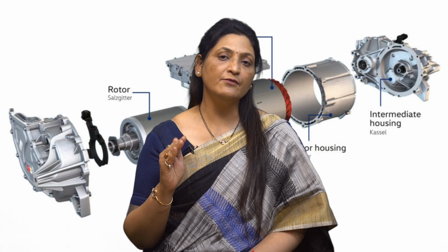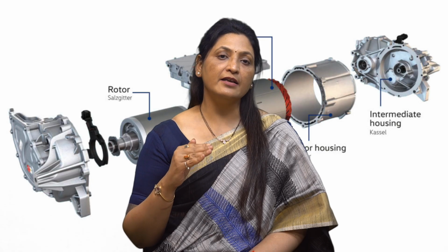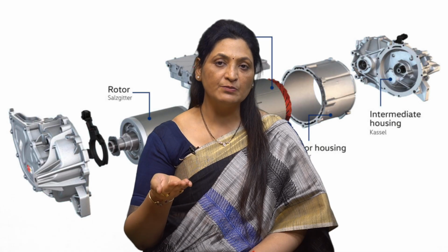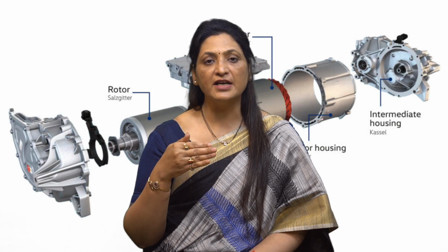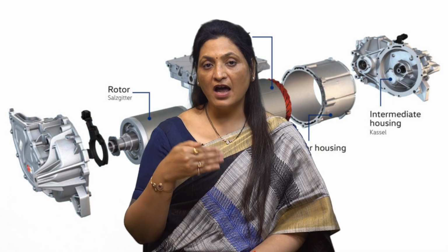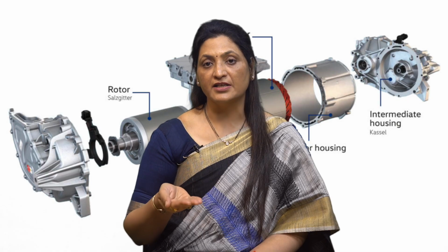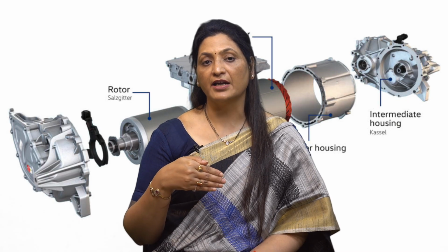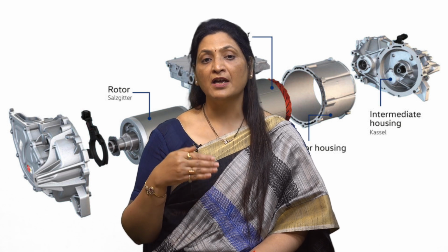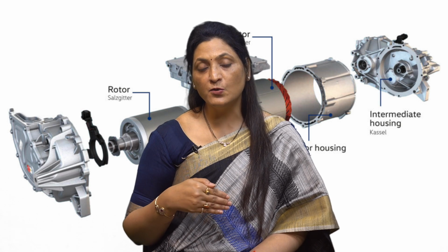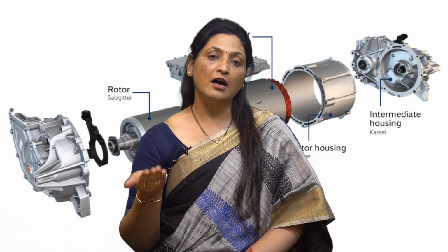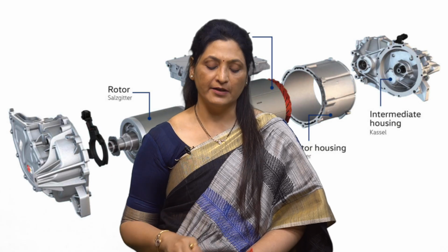The motors are designed for intermittent duty and they can cool down during the off periods. So, a higher power rating is possible compared to a motor that operates continuously. Then the ambient temperature, or the environmental conditions in which the motor operates, also affects its power rating. Higher surrounding temperature makes it harder for a motor to cool down. This requires either a reduction in power usage or better cooling techniques to ensure that the motor keeps working reliably.